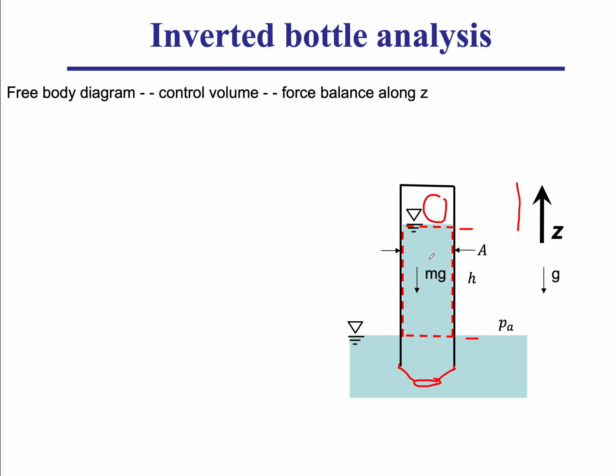Then I have, as you guessed, this imaginary line that I've drawn here is in touch with the fluid at the bottom, and the fluid at the bottom acts on my control volume, because it's a static fluid, only by a pressure force, not a shear force. That pressure force is compressive and perpendicular, so compressive, pointing towards the surface, and at 90 degrees.